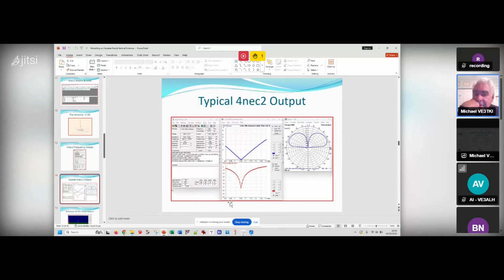Not all that much different, but when I put it up, I set it up in the backyard and got the thing where I wanted it to be. Then I took it up to the campground and set it up, and the lengths were different. I had to adjust the radials to get it right. That's probably the trees around; there's a fair amount of open space where I set it up, as opposed to the backyard, which was sort of crowded. So I did have to adjust it.